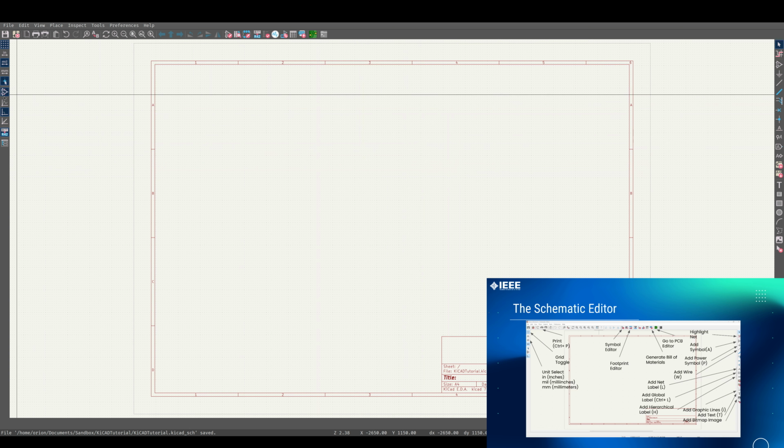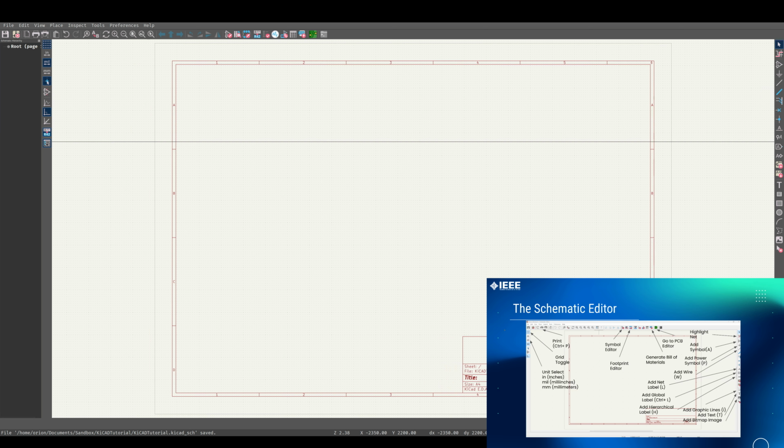This shows invisible pins, which doesn't really matter. This is a KiCad 7 exclusive. If it's 6, you won't really have an option here. This determines how you can route things, but by default it'll be 90 degrees. If this is here, you want to leave it on. This is a KiCad 7 thing as well. In KiCad 6, this won't be here. Same with your properties or schematic hierarchy.